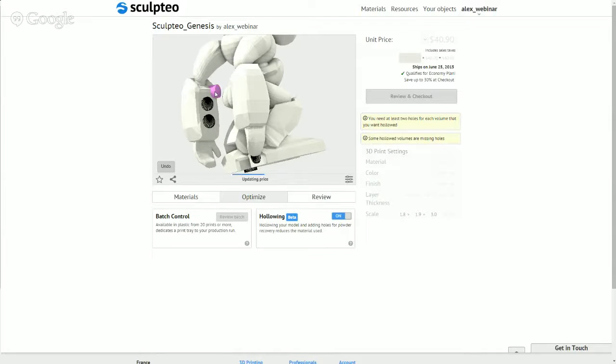It's very, very solid. And if you only have one hole, the powder particles build a kind of arch around the hole. So you need to have a certain size of hole. And you also need to be able to apply pressure from the inside, which you can only do if you have a second hole to blow air in.